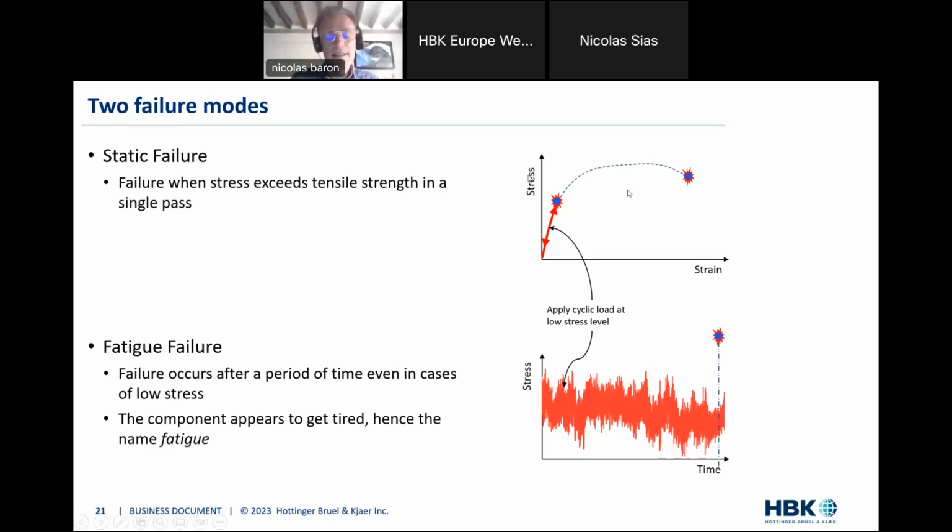As I said before, fatigue doesn't really need a high force. Here, when you have a high force, such as this one here, you might exceed the tensile strength. So you are just imparting a very high value force or acceleration or whatever the loading is to your component, so that in one go you reach breakage. So the failure really occurs immediately, so to speak. So in one go, that's static failure, and that is not fatigue failure.